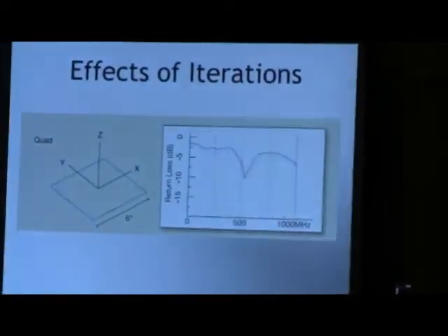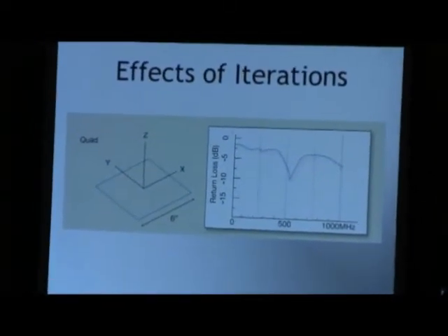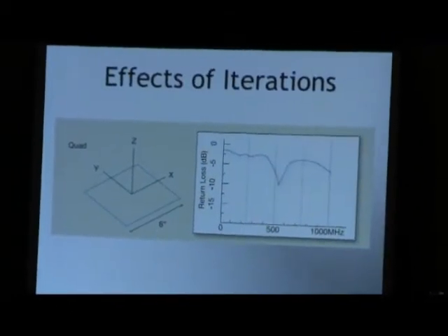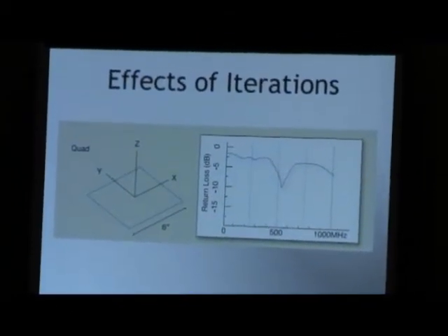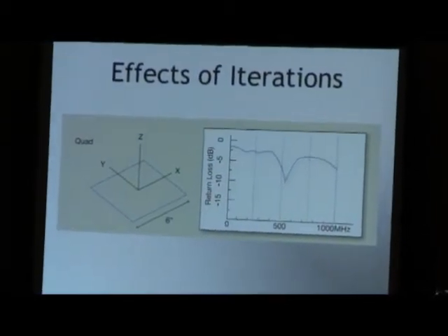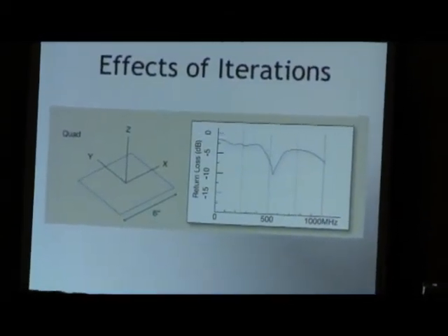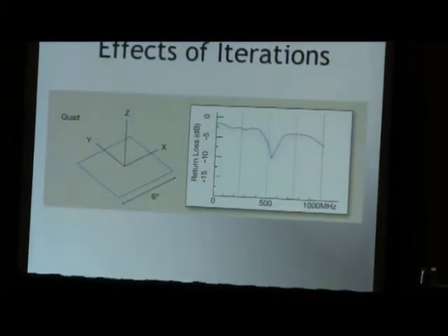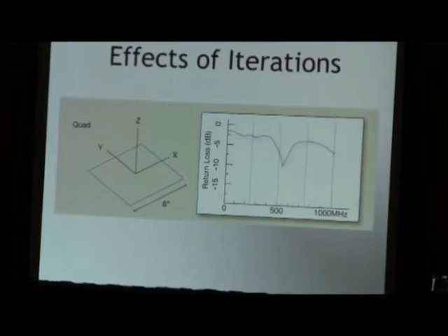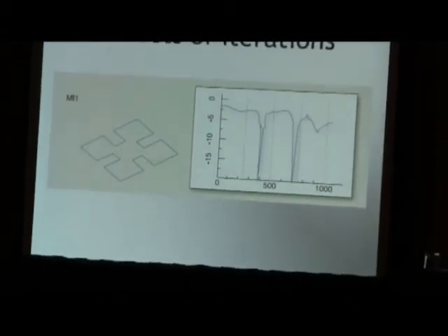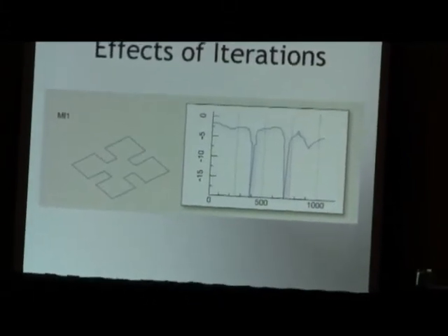And when it comes to any antenna, you want the incoming power from your radio or your transmitter to be fully radiated by your antenna. And the dip on the graph here indicates the least amount of reflected power for the antenna. So you'll notice that there's nothing intrinsically special about this antenna. But take a look at what happens when I add an iteration. All of a sudden, you can see that this antenna is tuned for yet another frequency.